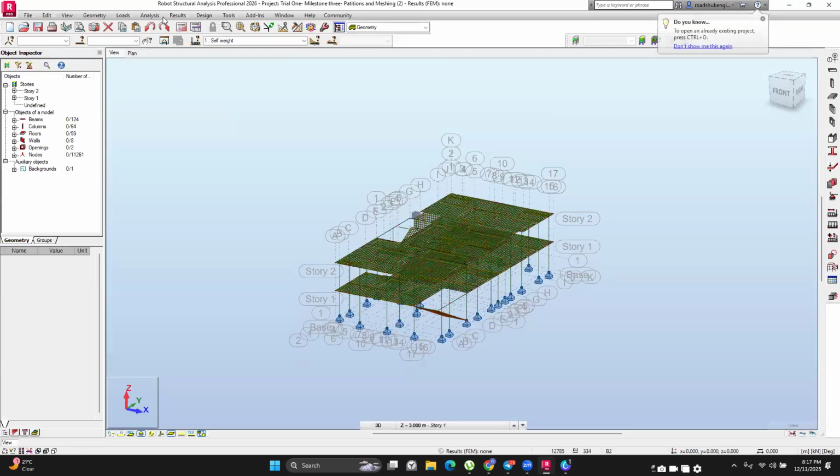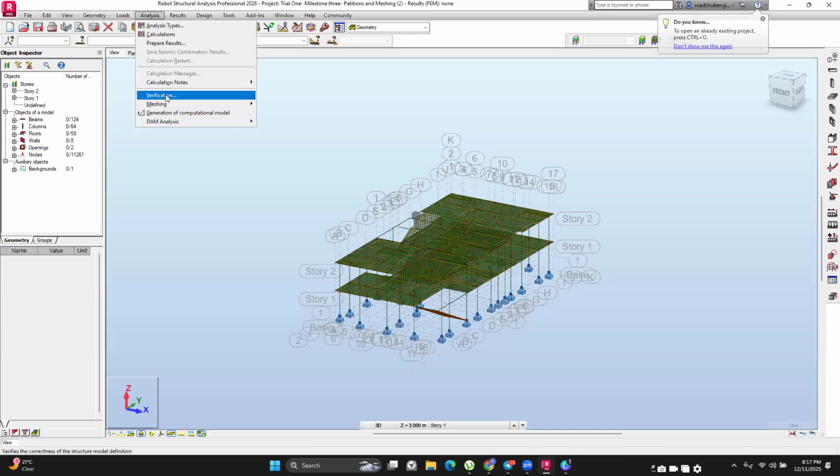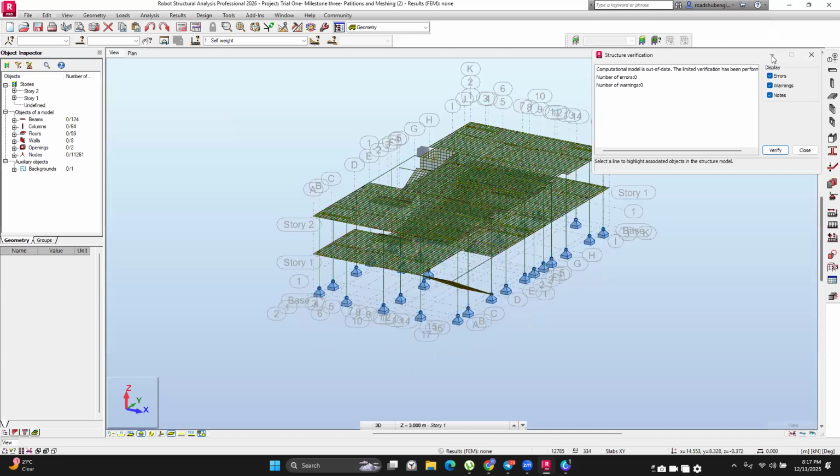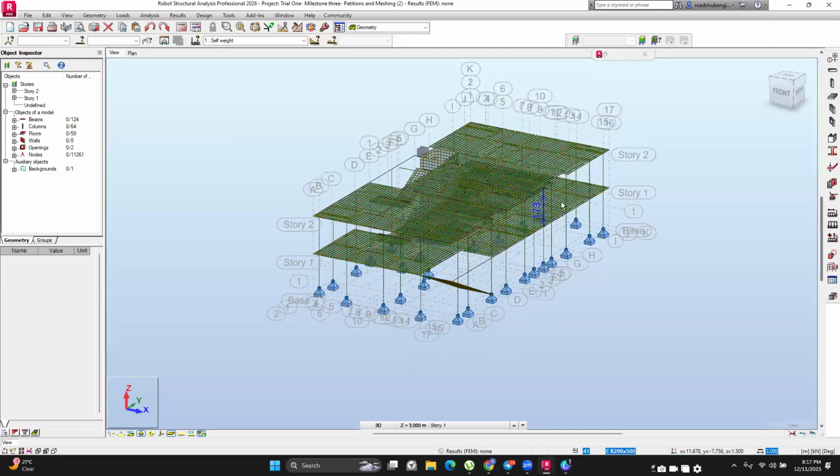So in the previous class, we were able to have no warnings. That's good. We started with modeling the foundation walls. We said that our structure is a 5-story structure with a basement floor. For the basement floor, we expect to have soil acting from the outside, pushing the wall inside, and we need this wall to be able to resist those loads.